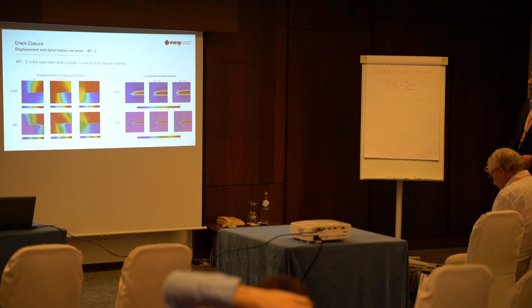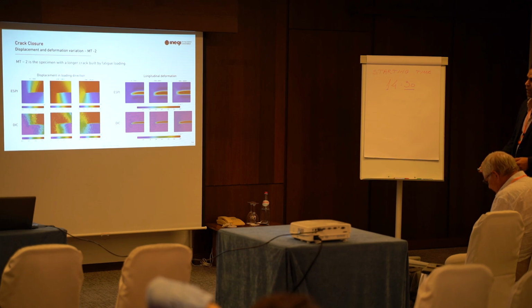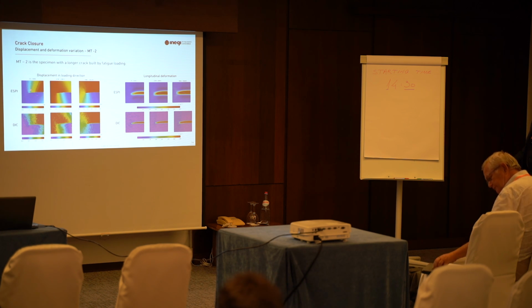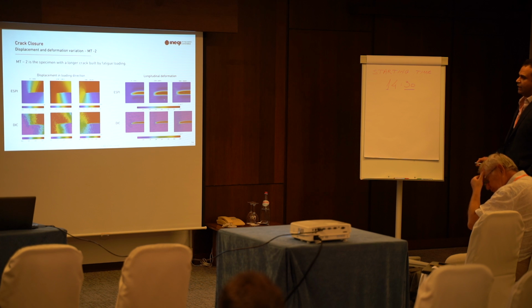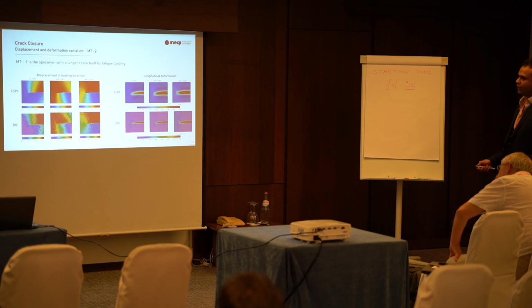But the scenario is different from the other specimen with the long crack. It shows that even in the minimum load, the crack is open. So it means that the plastic effect is too dominant on the structure, and it does not allow the crack to close, and the crack has already stabilized. And the results of the deformation put more evidence on that. So here in the minimum load we have the crack, because here is the notch and here is the crack. Although the crack is not completely open at this stage, we have the crack.